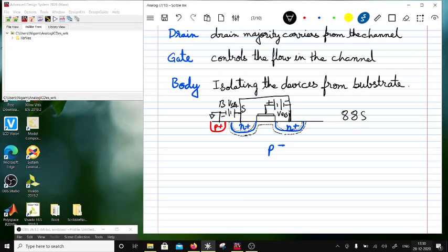So let's say these are dipoles, and I am drawing the blown up picture of the gate. This is the conductive portion of the poly. If I apply a positive voltage here, then the dipoles are going to align this way, plus plus plus plus plus, and this causes the electrons to escape from source and the drain and form a small layer underneath.